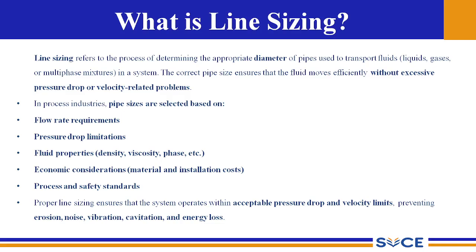Next is the material and installation cost, which needs to be worked out for different types of materials suitable for our application. For example, we may go for alloy based materials, or we can use the line with some cladding or coverings which may prevent erosion or corrosive damage. The economic considerations involve the various materials and the installation cost associated with them. So we need to work out the entire costing before choosing the material and installing the pipeline.